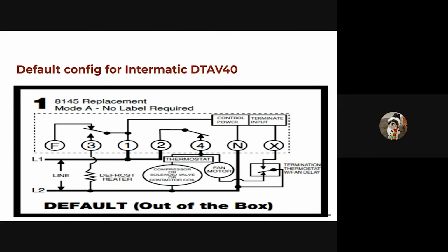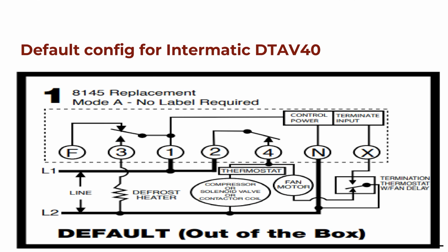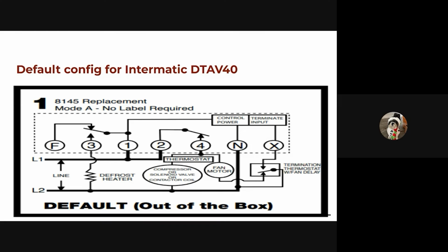Right. Yep. So in the sense of this system here, what I was thinking is that with this thermostat there's going to be a natural time delay until it gets to the right cooling temperature to move it. So I guess two things are going to happen there. One, you're going to allow time for it to drip before you turn fans on, and then push those droplets of water out into a space.